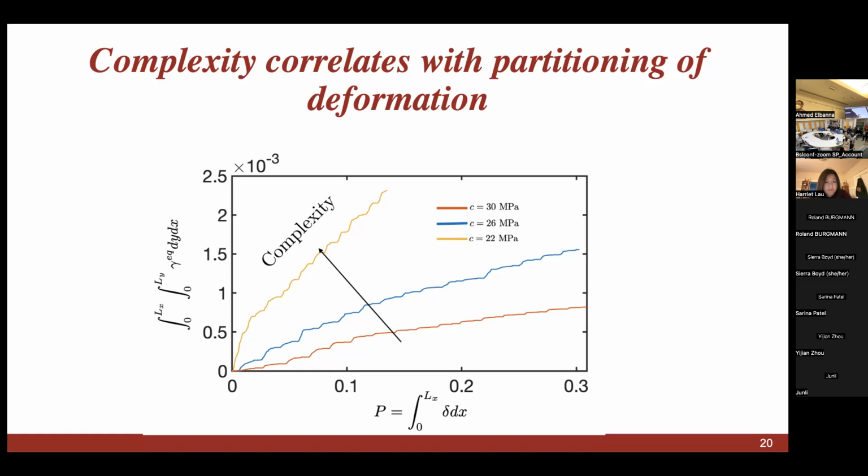So you could think of this not as plasticity dissipating a lot of energy, but the more important effect, at least in our model, is that plasticity caps the stress. And when you cap the stress ahead of the rupture tip, you deprive the rupture tip of the ability to concentrate the stress further as it propagates, and hence this acts as self-arresting.